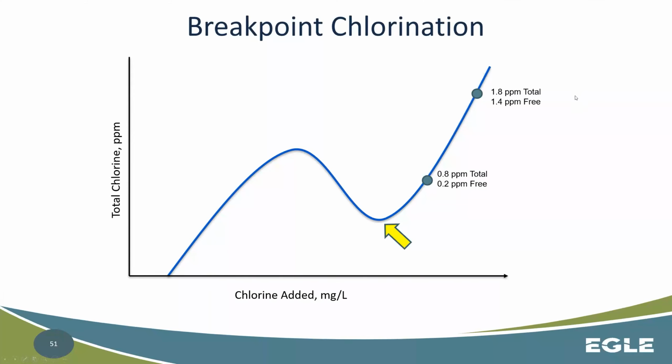And you should be able to have somewhere up to about 4 parts per million of chlorination into a system before it's readily detectable by the majority of the population by scent or taste. Or not 4 parts per million. I've said that wrong. It's 2 parts per million. It's up to about 2 parts per million, I think is what it is, where you can get it up there into a point where the population doesn't really smell and taste that chlorination at all. They can't really detect it.